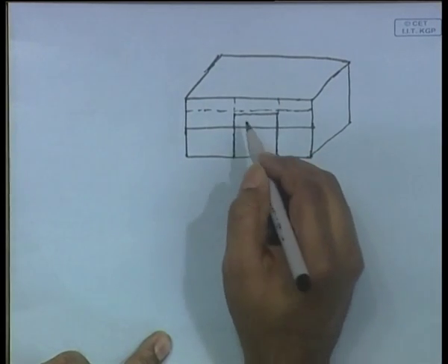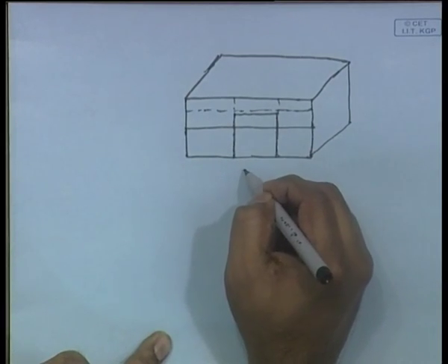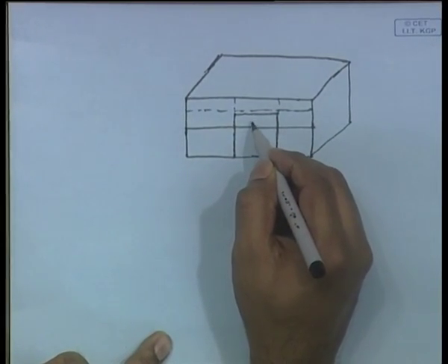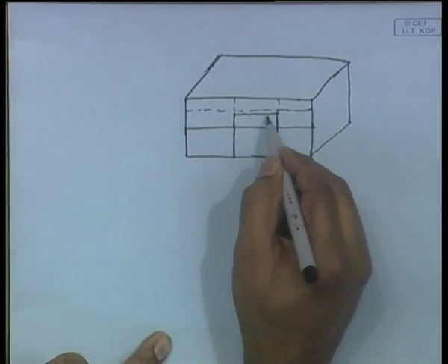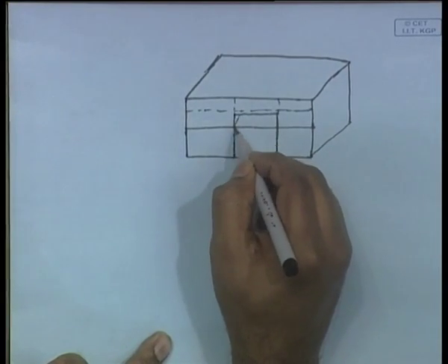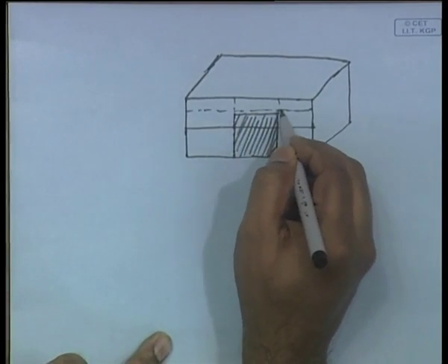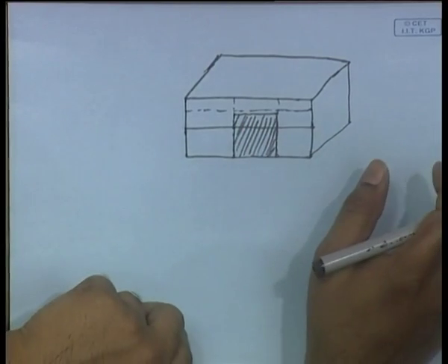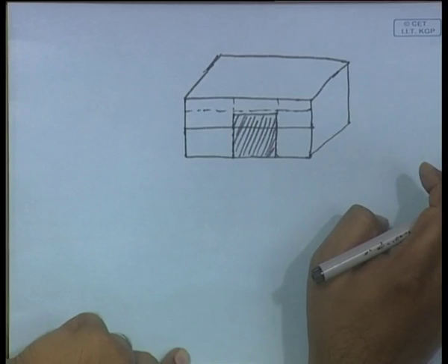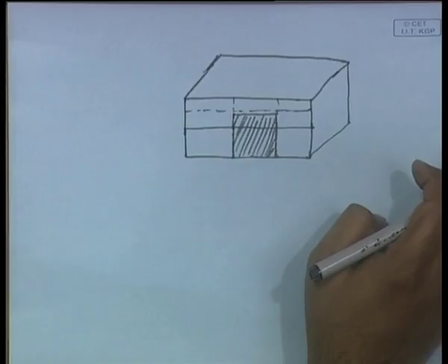In this problem the difference is that they have put a flat here, some kind of ceiling, such that when this is bilged, water cannot go above it. It is a watertight flat. So even though the draft is up to this much, in the compartment water will be only up to this, and the region above will be just like the other ship which is not at all bilged. That is the difference in this problem, just a slight twist. The difference will come in trying to calculate things like I and the height up to which it is bilged. That is the only difference.